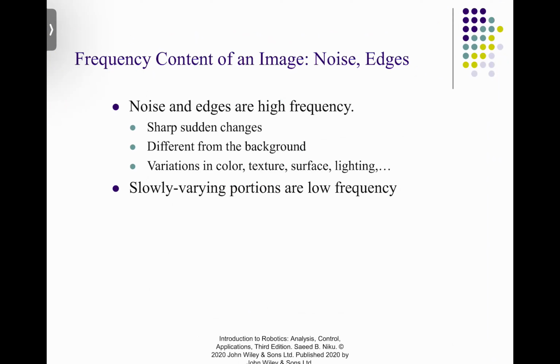Now, why do we need to perform this frequency analysis? Because when you decompose the signal, it's very easy to manipulate the signal. I give you a very simple example. Imagine if a signal has very high noise. Noise is usually a high frequency signal. So if you were to pass that contaminated signal through a low pass filter, then that high frequency noise will get filtered and only the clean signal would come out.